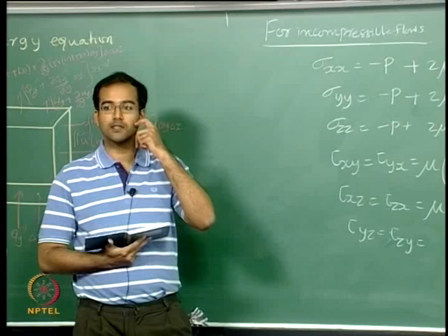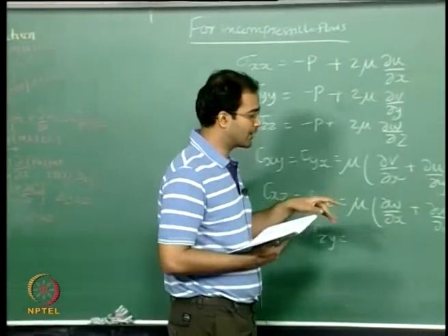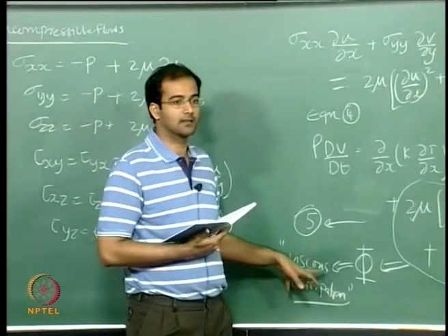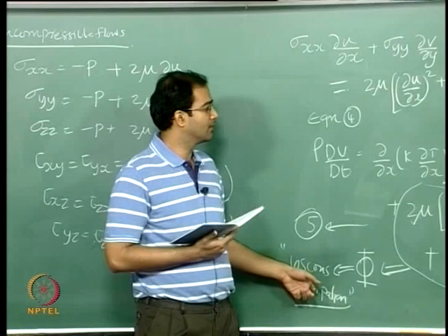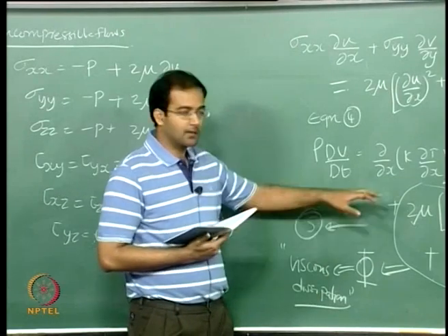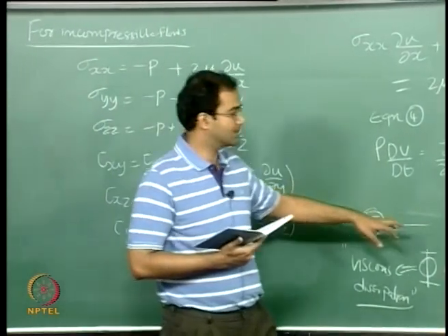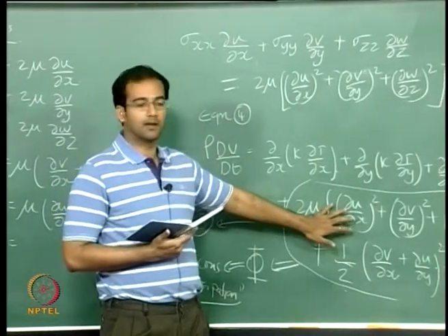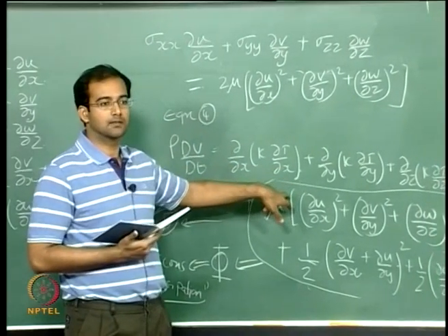So only the viscous forces, the surface forces, play the role, and they are all grouped together as what is called the viscous dissipation contribution to the internal energy of the system. Now some people make an approximation that under certain criteria and conditions this is going to be negligible, and therefore you can see the familiar form of the energy equation.